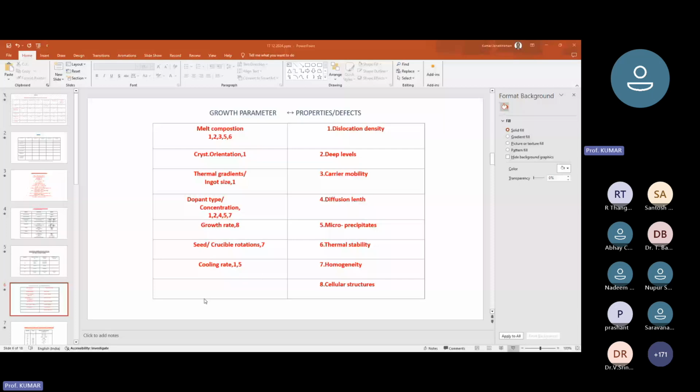Say, for example, if I take germanium or silicon or even carbon, in some cases tin, in these cases, you see, I have put N bar P, which means it is an amphoteric dopant. So this germanium or silicon can occupy both gallium or arsenic site or indium or phosphorus site. So naturally, it will either become N type or P type depending on the site occupancy. So one has to be very careful in selecting a given element in order to make it really N type or P type.